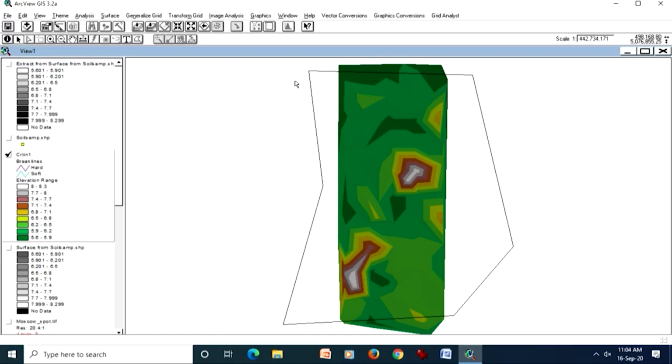So that is one of the limitations with the TIN. However, as I have said, if you are ultimately going to make a subset, it is better to first make the subset of point data and then create the TIN. There will not be any big problem in that way. But the boundary issues will always be there.